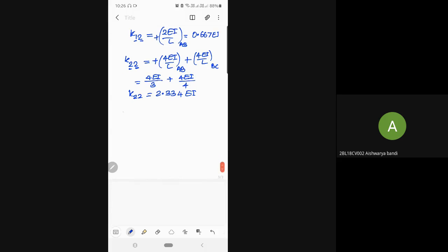So now you have got all the elements. Therefore, your stiffness matrix K is K11, K21 in the first column, and K12, K22 in the second column. You can see this is 1, this is 1, this is the first column. This is 2, this is 2, this is the second column. 1 is unit displacement at 1, 2 is unit displacement at 2, and the rows are the forces at 1 and 2.